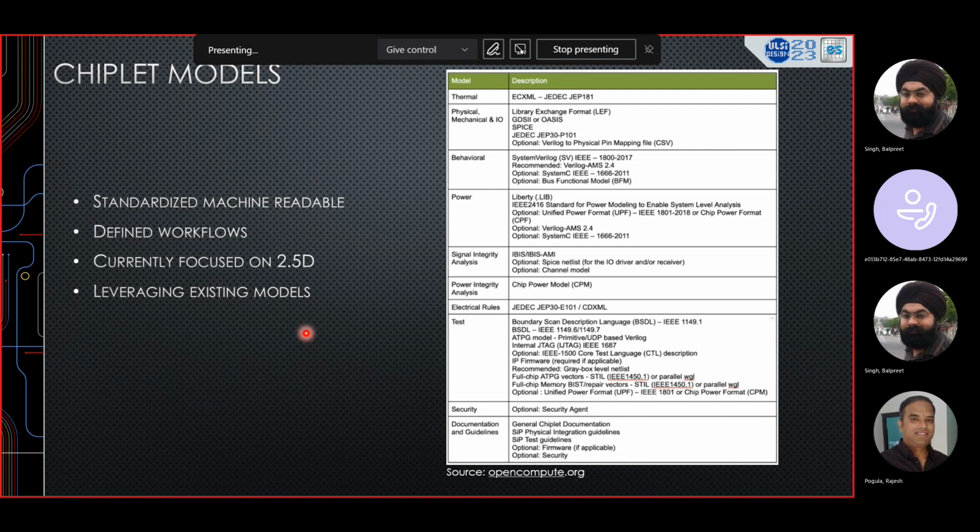One is to do a high density interconnect talk between these two dies or multiple dies, and also to do the micro bump, which Biswajit talked about, to the C4 bump conversion as well. That's what the interposer is doing as well, right? So you still have a stack there in the 2.5D. Yeah. In some cases, depending on how they look at it, you can also call it 3D, but they're calling it 2.5D. But yeah. You want to add anything?